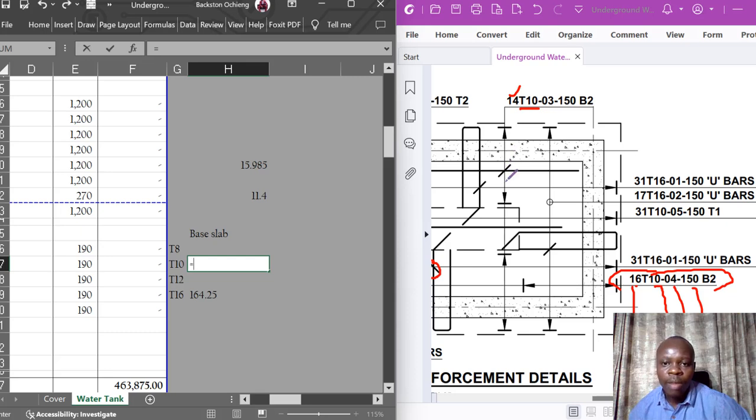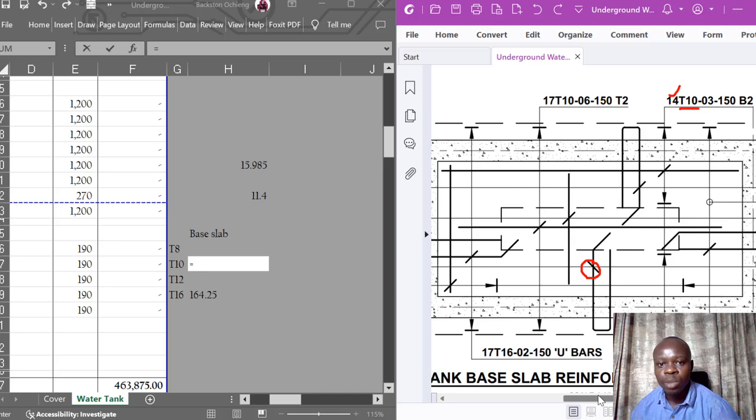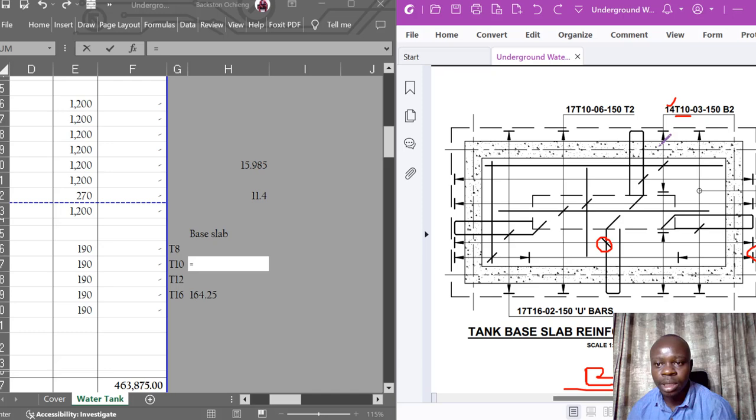Okay, so the part where there is this particular mark, at times it might be a very thick dot, and you also notice the thicknesses of that line work. So moving this way, the bar is at this point. I hope you can see that as well. That is the reinforcement bar, the one that is perpendicular to the arrow. Please don't forget that. So our reinforcement bar is this one here, the one that goes all the way internally. There are 14 of them and they are T10.